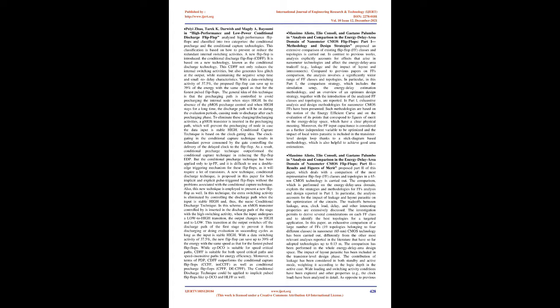A new technique, the conditional discharge technique, is proposed in this paper for both implicit and explicit pulse-triggered flip-flops without the problems associated with the conditional capture technique. Also, this new technique is employed to present a new flip-flop as well. In this technique, the extra switching activity is eliminated by controlling the discharge path when the input is stable high and, thus, the name conditional discharge technique.